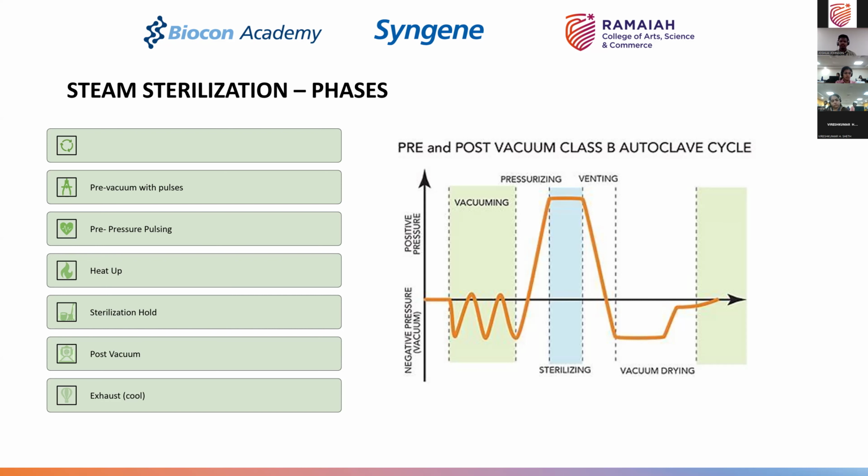That is why you have an aided cycle of vacuum and sometimes jacket cooling to cool down the chamber after the initial venting has happened, so that you can achieve the right drying inside the chamber and the right temperature, so that the load can safely be removed without harming the person who is handling it.